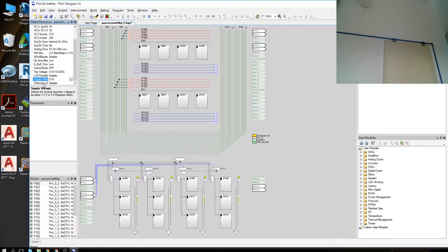You need to clear it in software. So in case there is something going wrong in your code, it would mean that you haven't been feeding that watchdog for a while. And then the watchdog actually takes over and eats you. So it goes and resets the circuit.